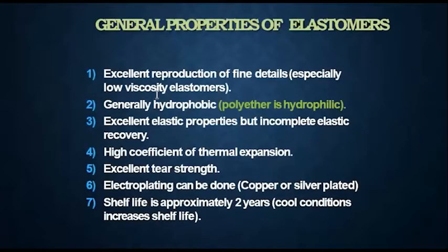Coming to the general properties of elastomers, they generally have excellent reproduction of surface details, especially low viscosity elastomers. Based on the filler content, they can be classified as told earlier: extra low, low, medium, heavy, and putty. Generally, they are hydrophobic, that is, they do not absorb water, except polyether, which is hydrophilic. They have excellent elastic properties, but incomplete elastic recovery. They have a high coefficient of thermal expansion. They have excellent tear strength. Electroplating can be done using copper or silver, and the shelf life is approximately 2 years. Storing in cool conditions increases the shelf life.